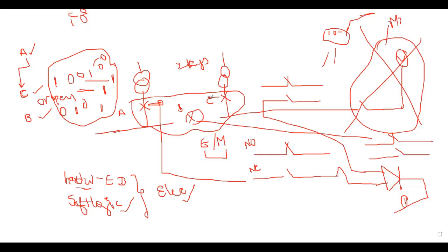And if I insert the key to this one, then only I can switch it on or off. If there is no key, I cannot switch this breaker on or off. This is a kind of mechanical interlock, which is coupled to the fixed contact or moving contacts directly with some mechanical interconnection.